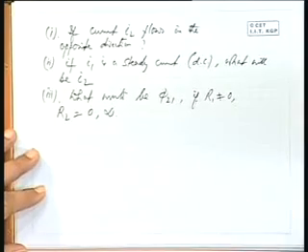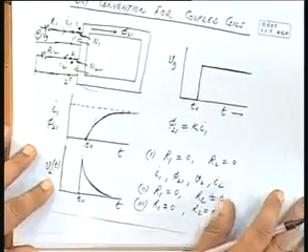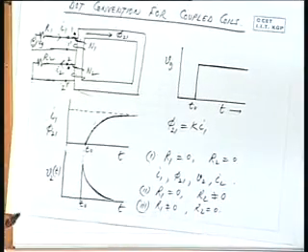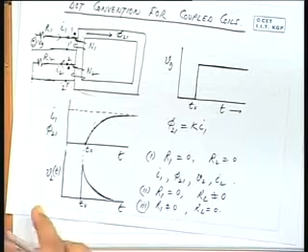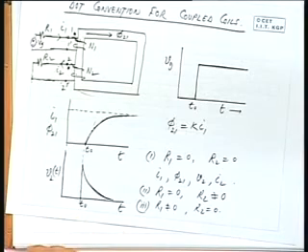Okay. One or two we will discuss here because they are very relevant. Sometimes by mistake you may put a DC supply onto a transformer. Suppose the transformer is open circuited. So what happens to the transformer? Or say you are going for a short circuit test, transformer secondary terminals have been shorted and you are supposed to apply a very small AC voltage on the primary. Instead of that you apply a DC. What happens?